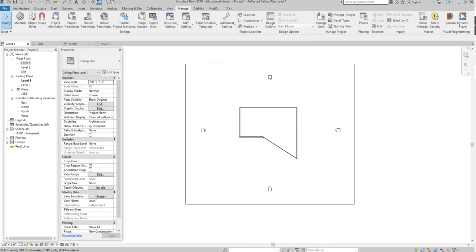And I now know that my units have been defined as they should be. Okay. One thing I do also want to define while we're on the topic of units is that in Revit, the foot is the default unit, right? This takes some getting used to when you've been using AutoCAD, where the inch is the default unit, okay?